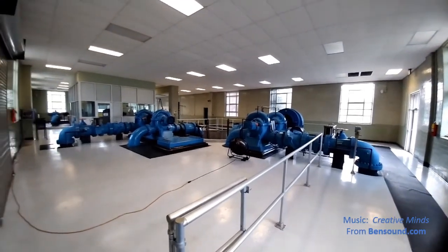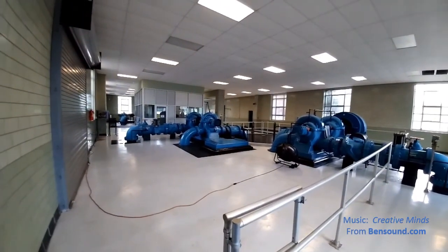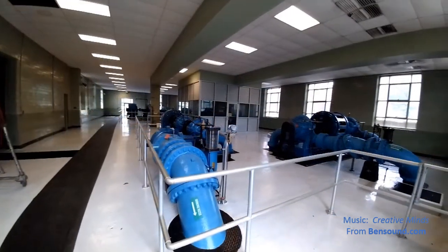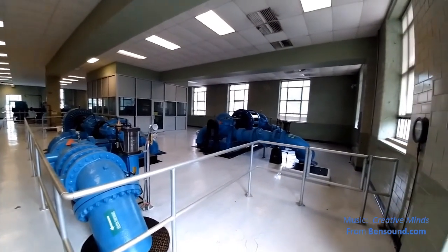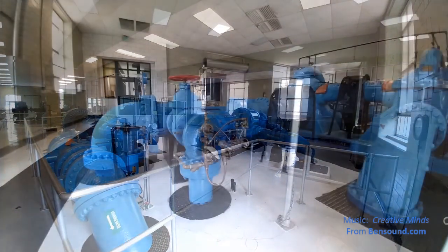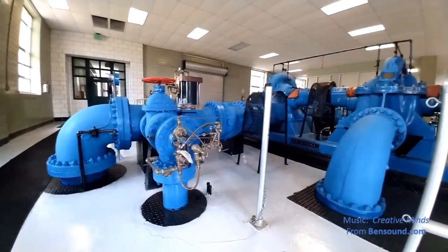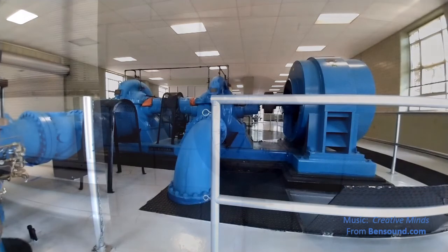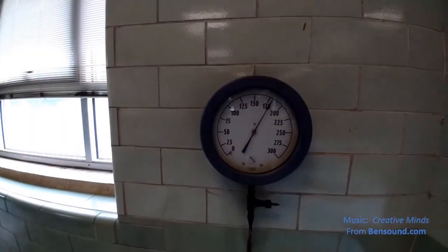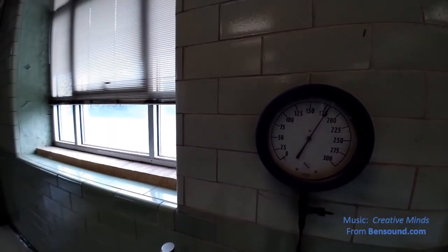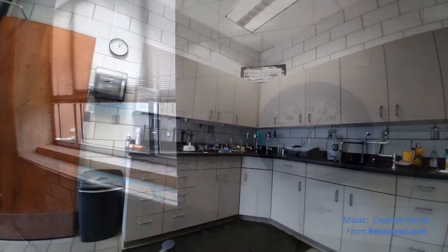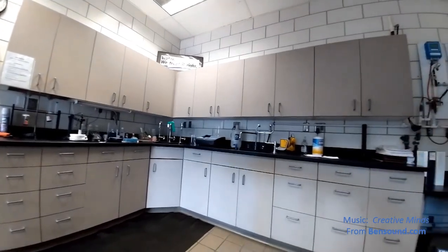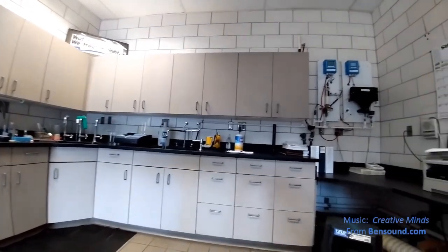The finished water is then pumped to the distribution system using a combination of 4 large high-service pumps. These pumps use 2400-volt electric motors up to 1200 horsepower to transmit up to 23 million gallons of water per day. Many parameters are measured throughout the day, such as pressure, and in our certified laboratory, we monitor water quality control characteristics, such as pH.